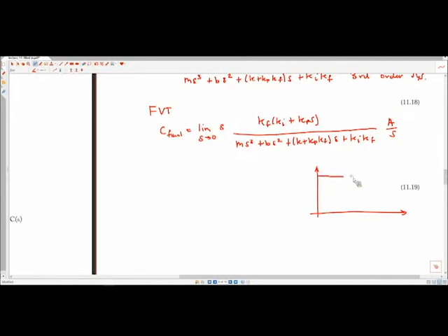So say here is R of t, and C of t just never reaches this for whatever reason, right? And now your error signal is R minus C, which is the error signal. And so you're saying if we were to integrate this, the integral of this is this function, and there's going to be a term in here that's going to continue to build and build and build, right? Okay. So yeah, this is what's called integral windup.